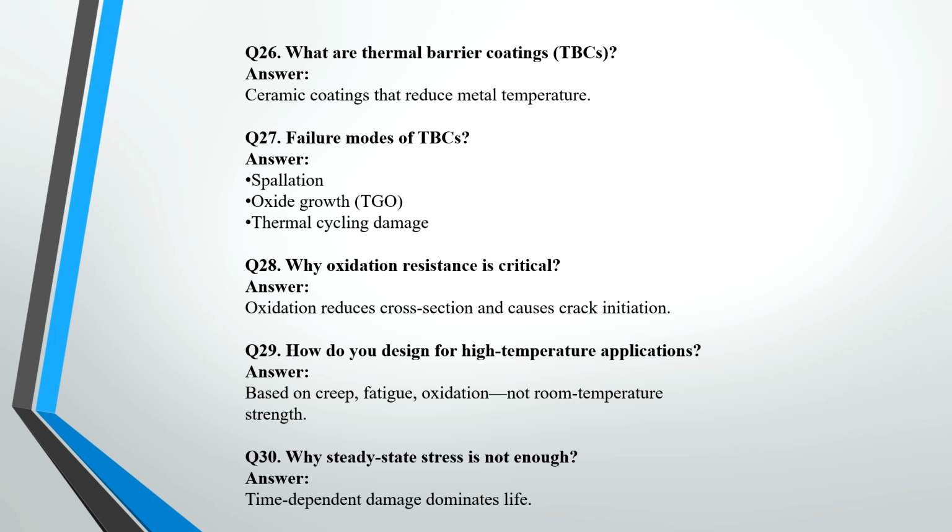What are thermal barrier coatings? You might have heard about thermal barrier coatings. It's a ceramic coating that reduces metal temperatures. What are the failure modes of TBC, thermal barrier coating? One is spallation, another is oxide growth, and the third one is thermal cycling damage.